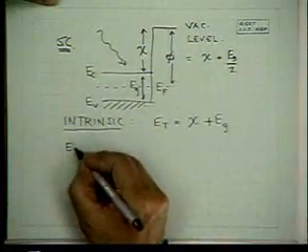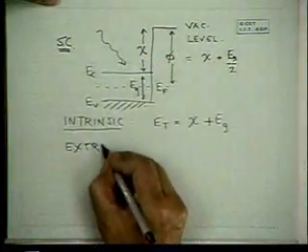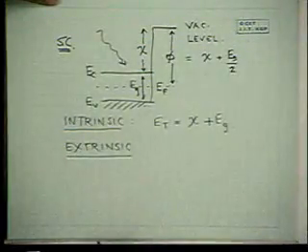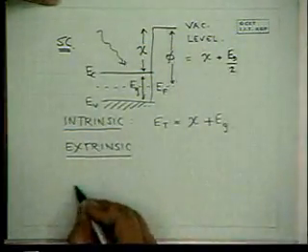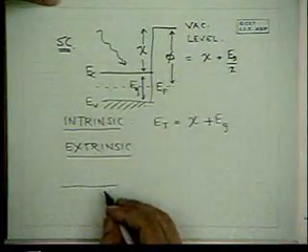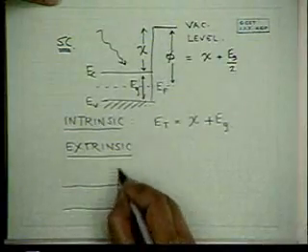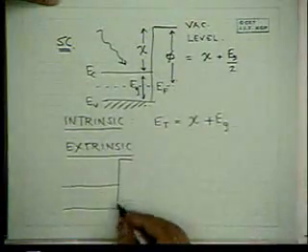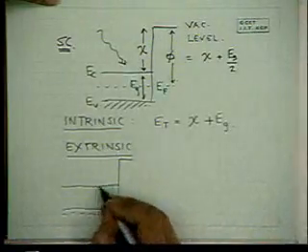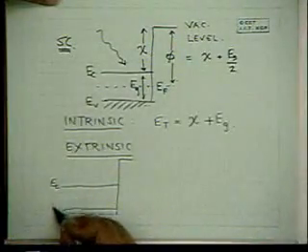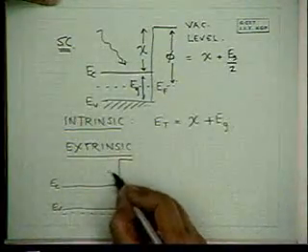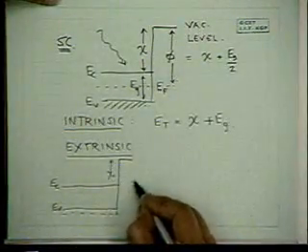If you take extrinsic semiconductors, it can be pretty easily shown that, suppose the material is, the important case is if it's highly doped p-type, the Fermi level can be degenerate, below the valence band. Okay, and what is Et then?